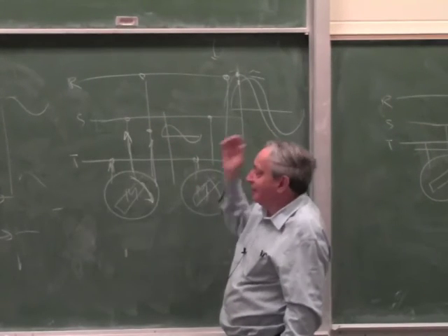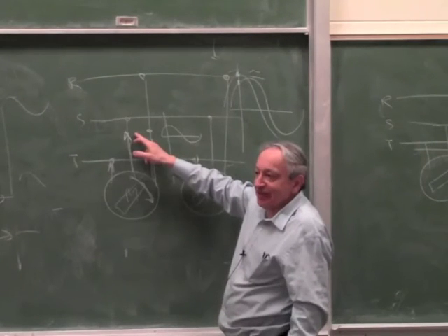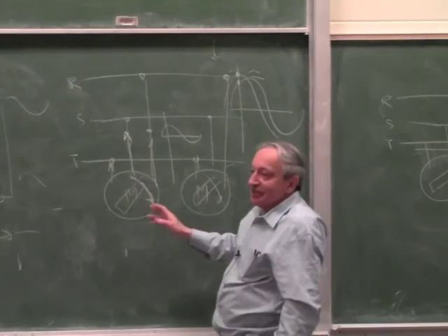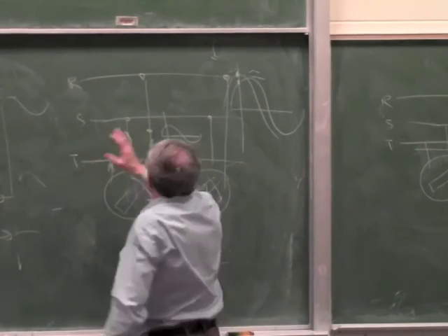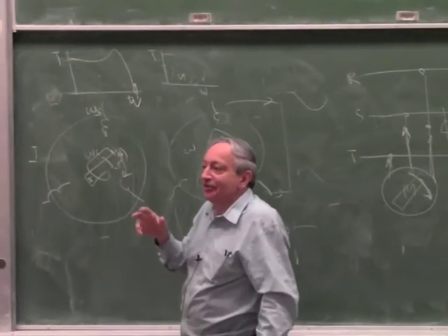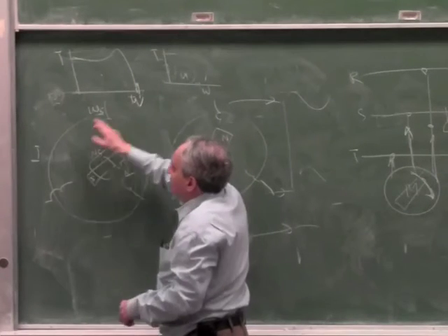So normally there is a power angle, and this is lagging the three phase, so power flows in. But if you reverse the power angle and it's leading, power flows back. So the same argument works here too, but instead of power angle, you have to reverse a slip. You have to make this go faster than the rotating field.